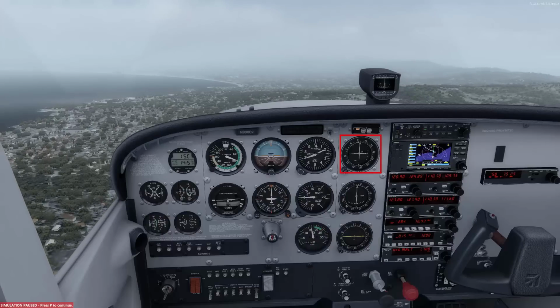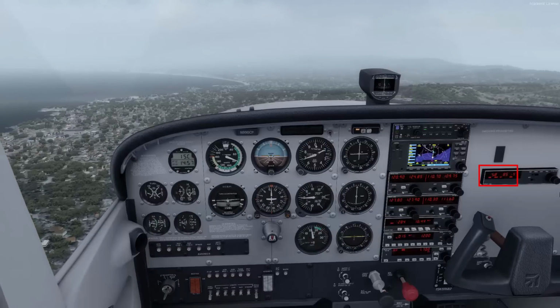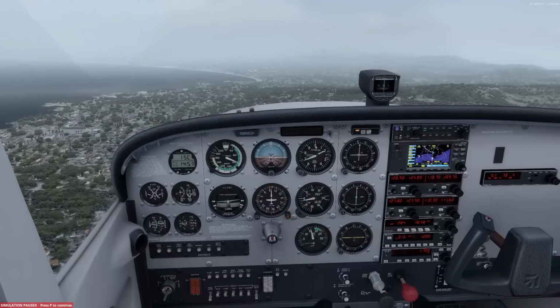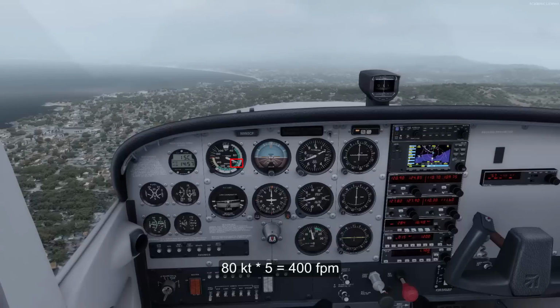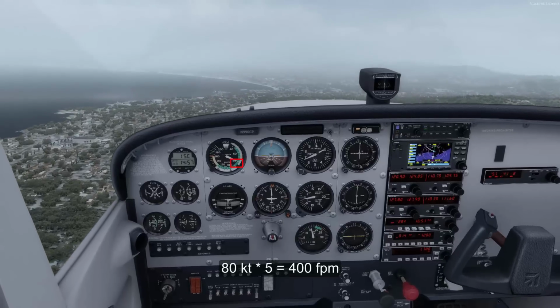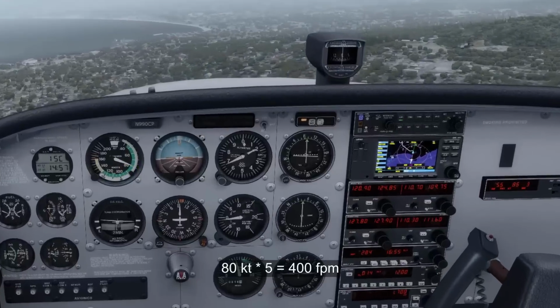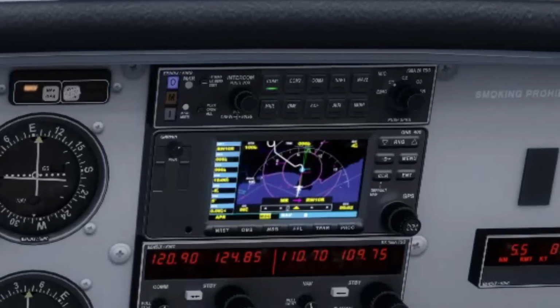We have intercepted the glide slope and are at 1700 feet altitude. This is the glide slope intercept point from the approach chart. We are at 5.8 nautical miles from the DME. A little before crossing the glide slope, we can start descending. The target vertical speed is approximately your speed times 5 to keep the 3 degrees glide slope descent.